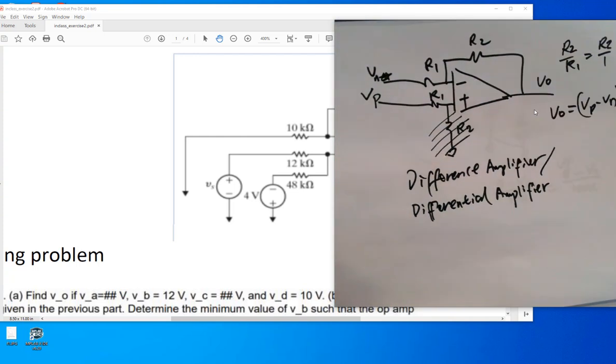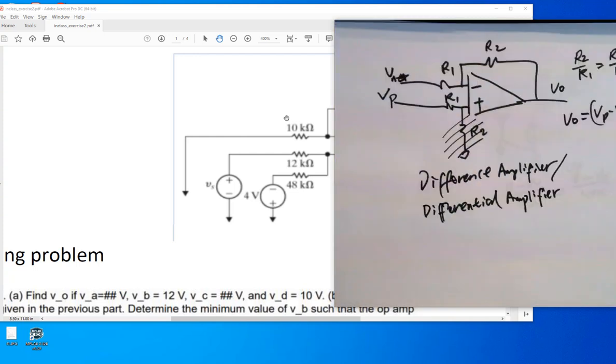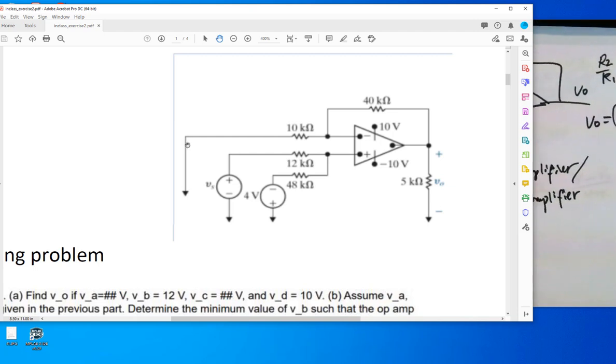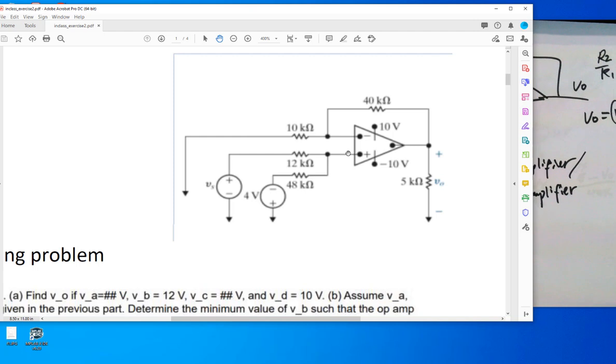In my knowledge, I either just use a very simple amplifier configuration. You ground the other point and just use it as a low quality non-inverting or inverting amplifier. Just make it simple, right? You don't have to consider the trace length to make it symmetrical. Just directly throw it into the circuit, it's going to work if you don't quite care about the quality of the signals. So these are just called non-inverting and inverting, okay?